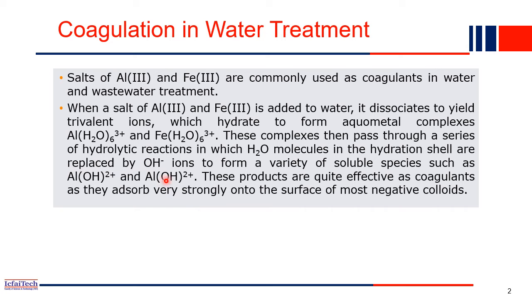So this type of complex particles or complex ions are basically attracted by the suspended particles. Here you see, in the water these small fine suspended particles are present anyway. So when these complex ions are produced because of this chemical reaction, they are absorbed by each particle. The suspended particles will absorb these ions because the particle is very fine. Very fine means very small.